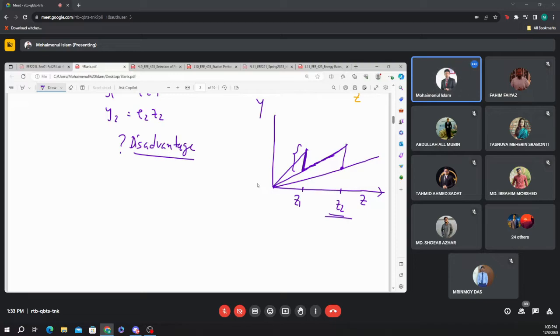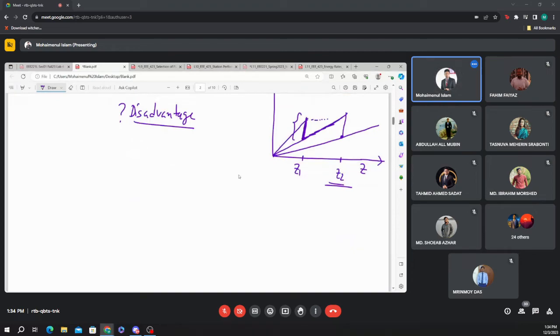Rather we want to increase the price. So here, rather than it increasing, we should make it flat, make it constant up to the next level. Then he should pay again linearly, he should pay more, but before going to the next level, the price should be constant. This type of arrangement should be there, rather than decreasing. So that is called modified step meter rate. Okay, so we can change the graph.